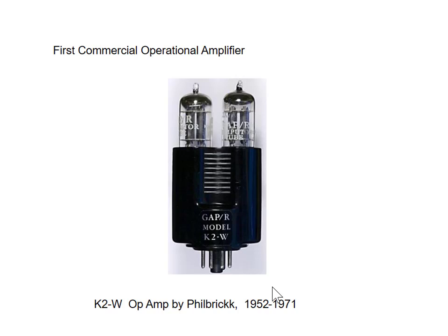Now, I mentioned I used to work in the filters area. At the time that people were building active filters, they used op amps. Op amp designs of the 50s and 60s were typically ones that said you can use one op amp in your design and have as complicated of an RC or RLC network as you want, but don't use more than one op amp in your design.